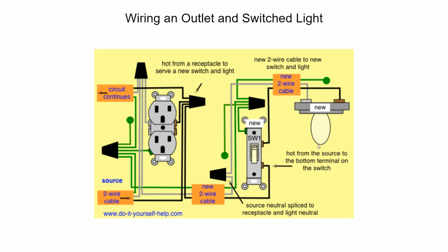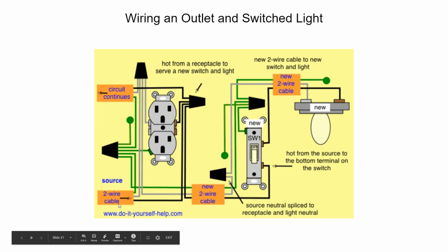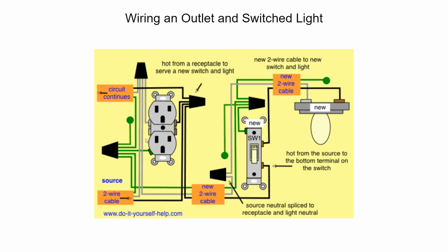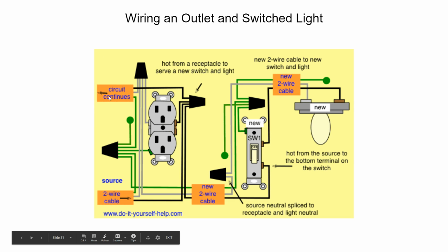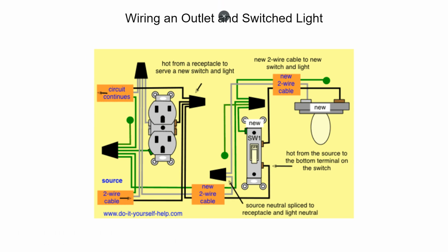So now we're going to put the two things together. This looks like a mess, but it's not, because we've talked about the constituent parts. We're going to have two wires come in. That's our Romex feeding from our panel. This right here is to another circuit someplace else. Ignore that. So you come in, first wire goes to silver, white wire goes to silver, first wire goes to black. Then right here, instead of coming off of here, we've decided to wire nut it.